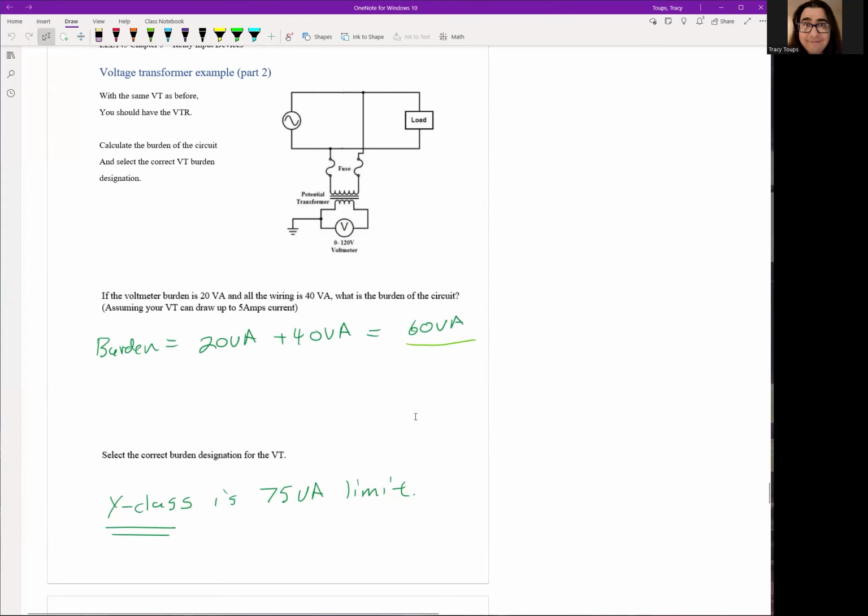Okay. One thing to note here is, if you notice, we didn't talk anything about the multi-tap ratios of X1 to X5. Typically, voltage transformers do not have those taps like CTs do. The main reason is that VTs don't vary in voltage too much because our system only has maybe 5 different types of voltages, and it doesn't make sense to make a more expensive variable voltage transformer because our voltages aren't going to change too much, right?